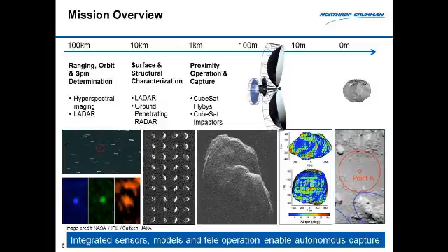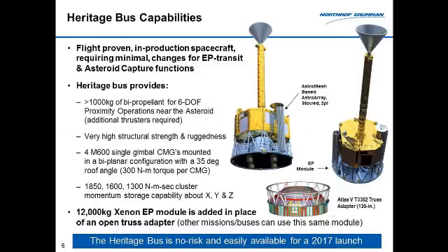want to contact it. And so the system that we came up with uses an existing spacecraft. It is a Heritage bus. It has 1,000 kilograms of bipropellant. It has the capability for 6-DOF, pretty high agility. It's really, really beefy, so it can handle that initial jolt. It has 4 CMGs that can be used or not that are massive, so it can maintain lock on that point and then use its 6-DOF system to spatially stay over that for a period of time so that the capture mechanisms that we're proposing can fully enclose and grab it. And that doesn't take that much propellant.